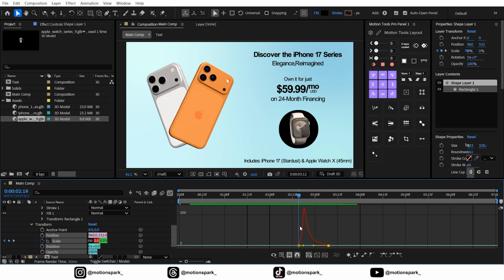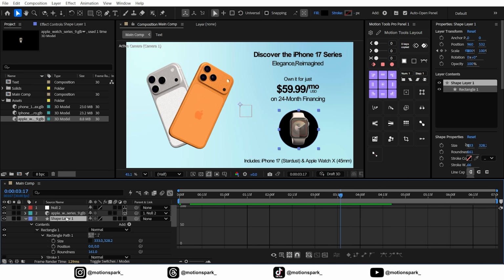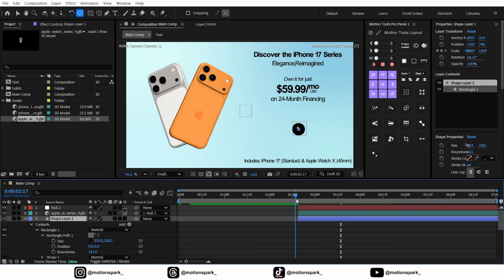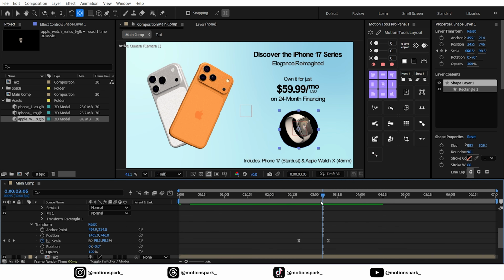curves of the keyframes. Right now, we have a minor issue in our scene. Because the anchor point is not in the correct position, the animation looks a bit off. To eliminate this problem, let's align the anchor point right to the dead center of the shape layer. This will completely fix the issue, allowing our animation to scale up flawlessly from the center.